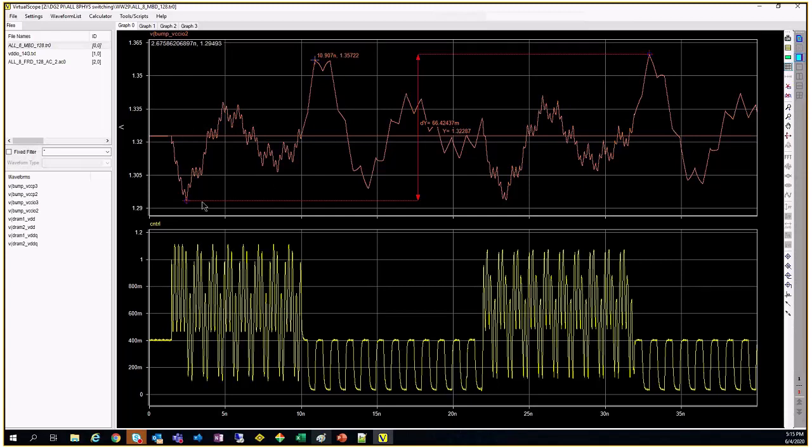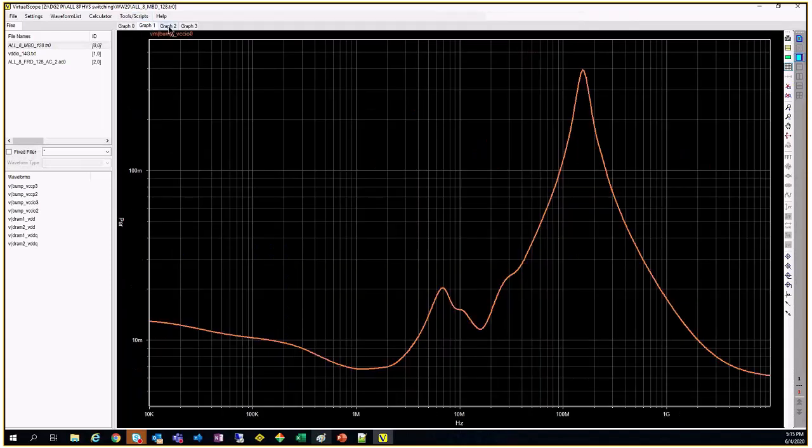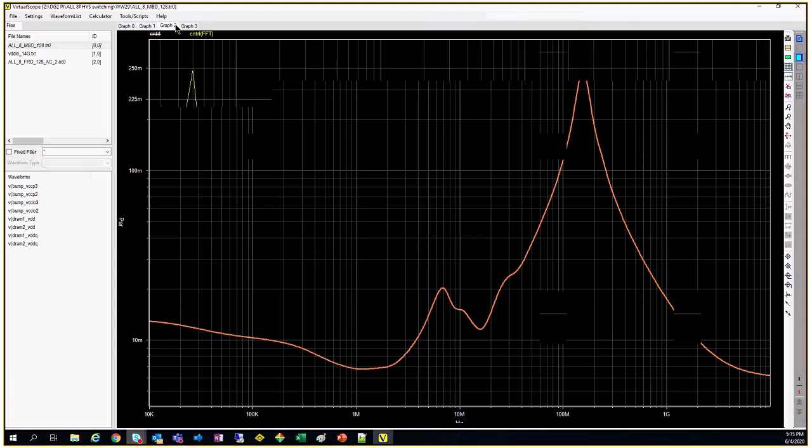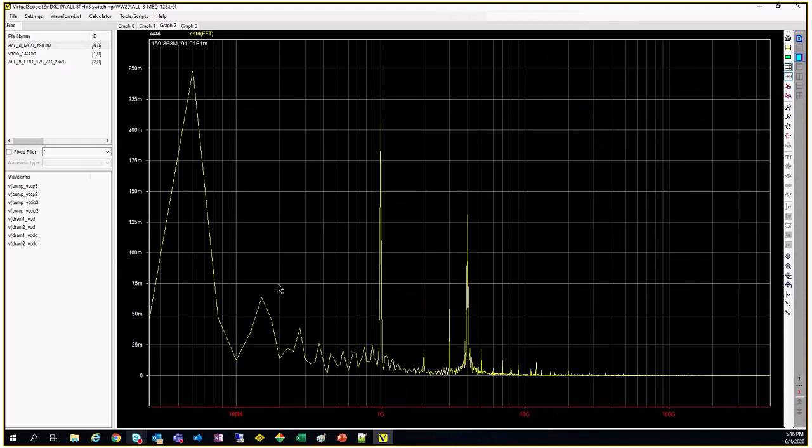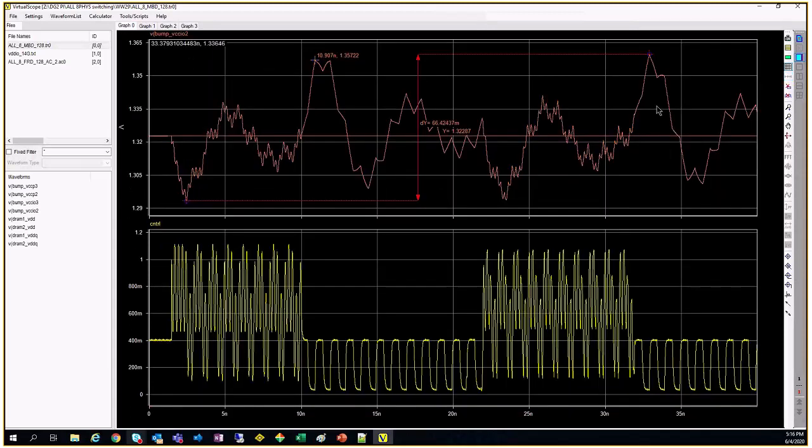So that is why most of your analysis will be done in the time domain. Frequency domain is more like a reference, like I told you. You look at what is done in the frequency domain, right? You look at the impedance in the frequency domain, compare it to the current profile you get, right? The current profile. And depending on that, you design your PDN solution to get the least amount of noise. That is what you're doing in SPICE.